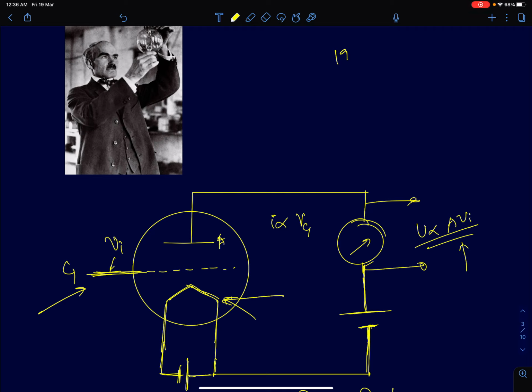I had already explained this, but any amplifier, all the three terminal devices which we have discussed so far, which is MOSFET, BJT, or a vacuum tube amplifier, has one terminal which generates carriers. It can be electrons or, once we came to semiconductors, both electrons or holes. But you need one terminal to generate carriers, another terminal to attract those carriers, and a third terminal to control the flow of carriers between these two terminals.